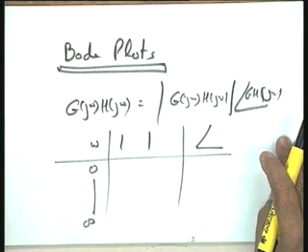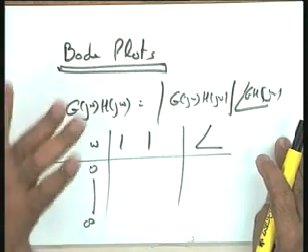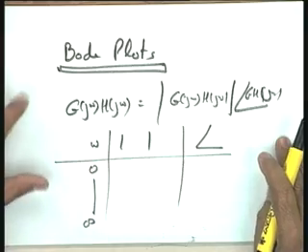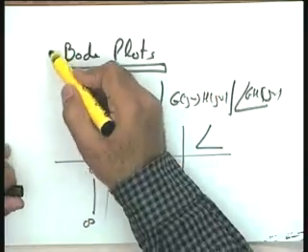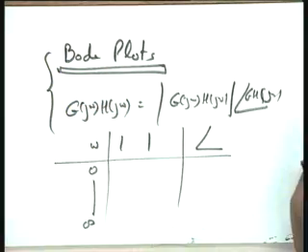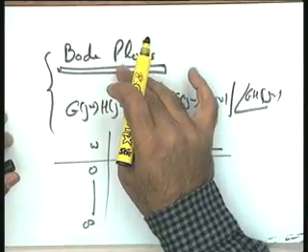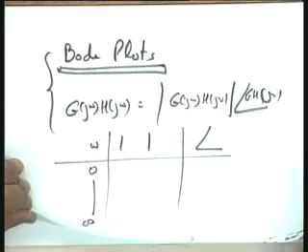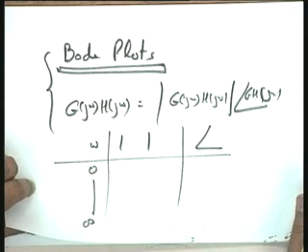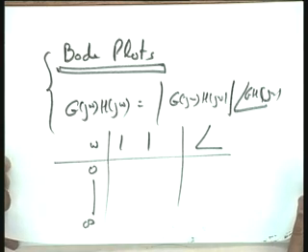So, the contribution of Bode is an extremely important contribution, because the frequency response design, the frequency domain design, is done on the Bode plot and not on the Nyquist plot. The two ideas are getting mixed, you see. The basic idea is given by Nyquist, the Nyquist stability criterion, but the use of the idea is given by Bode in terms of the Bode plot. So, from now onwards you will hardly come across the Nyquist plot in our discussion, because a tool which is easier than the polar plot will be in our hands as soon as I give you the constructional methods and analysis methods on the Bode plots.